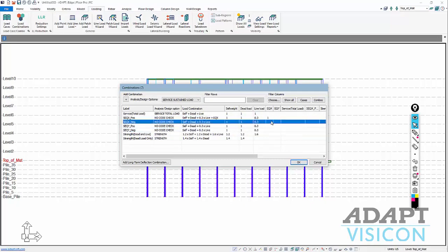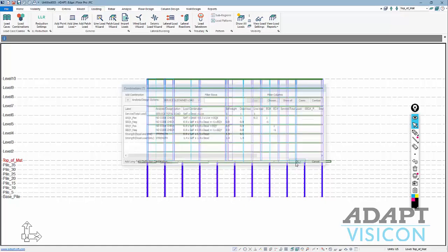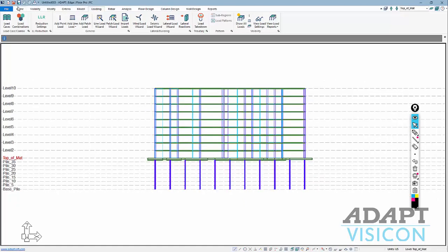So we would say this might be 1, -1, 1, -1, and let's assume we're using 0.9 times the self-weight and dead load, no live load on the structure. Okay, and then for this one, we'll do the same, 0.9 for our gravity loads, our gravity dead load, nothing for live load. And that sets the combinations we want to evaluate. I'll go ahead and save the model.